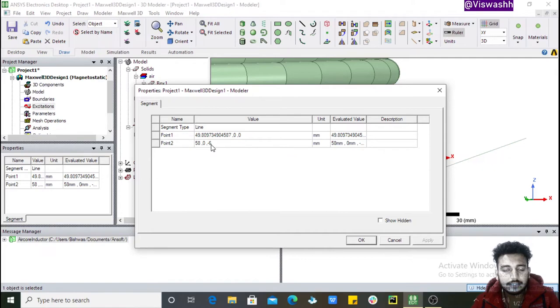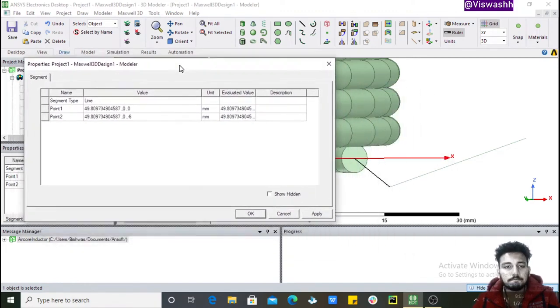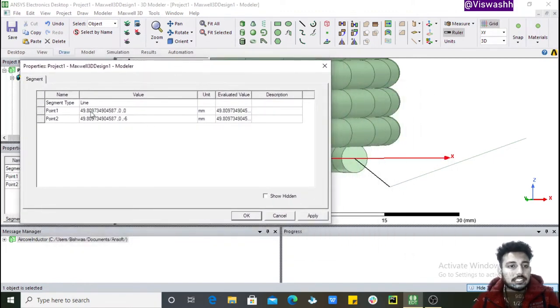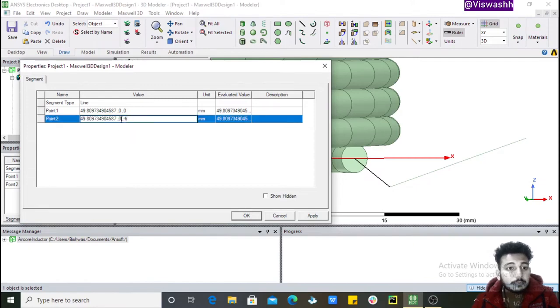So before pasting, here is -6. You might have doubts. So I won't erase that, but I will just copy the X point because for the X point you mandatorily need to copy that. You can use your mind and you can search why we did this, because it takes some time to get around what we're doing exactly to get the grasp of it. So you will be fine. And then the z-axis is actually changing, whereas our y-axis must be changing and z-axis must not be changing for the first line. Remember, it must be parallel to the xy plane.